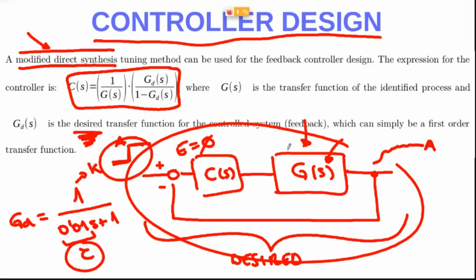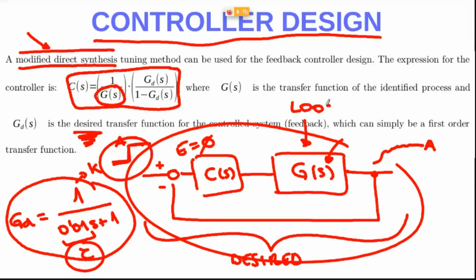So that's the idea. And what's the problem that will be associated with this? As you can see here, this transfer function is chosen by you. You decide what's the desired feedback performance. But this transfer function in here depends on the aircraft, and I can assure you that it's not so easy. This G of S is a long polynomial transfer function. Okay, it's quite long. It will be a high order polynomial.